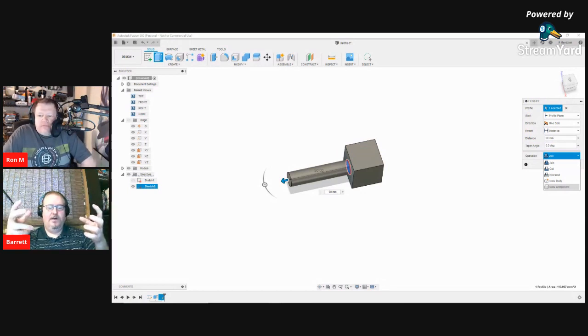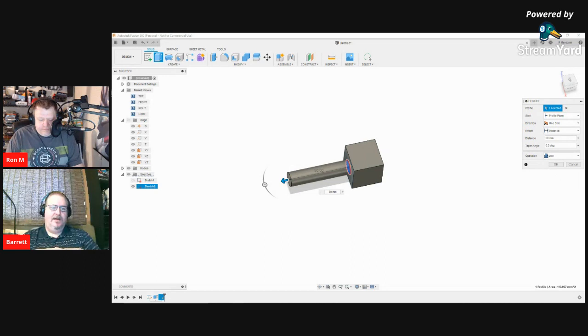That's really useful if you're trying to create a pseudo assembly within one document. You can directly create a new component. But typically what I'll do is create my bodies, and then select them and add them to a component later on as another step. But you can do it right here.